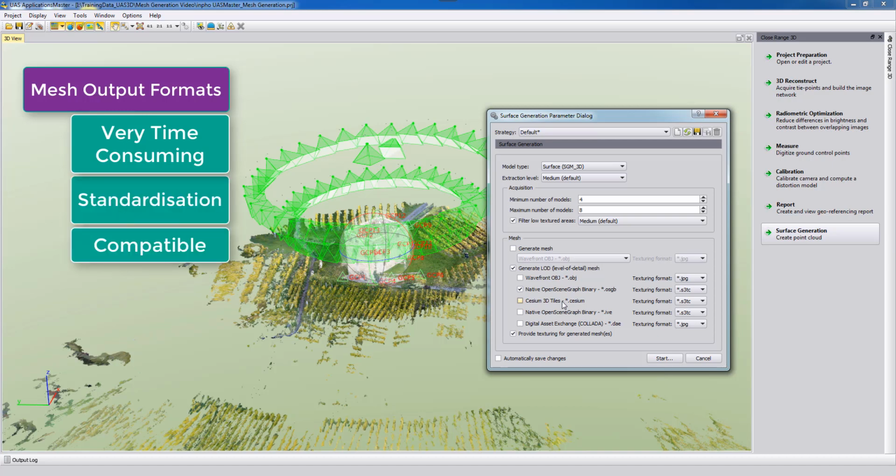In our experience, you have to be careful about standardization from the different formats. So not every Wavefront OBJ format is the same as the next one. It depends where you define your local coordinate system, where your X, Y, and Z axis are pointing to, and there are also many more things to be considered in this whole process.